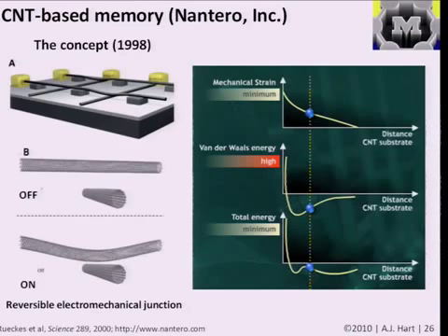And although it's very difficult to make these individual nanotube lattices, and you can't pattern individual tubes so precisely, what the company ended up doing is creating nanotube fabrics, and then using lithography, top-down processing, to cut them into very narrow ribbons, creating little strips of nanotubes that each contain many of them but behave in the same way. It's honestly not as dense, and not as inexpensive as the flash memory that we have, but for some applications, like things that go in space and take a lot of radiation, or need to operate in very extreme environments, high or low temperatures, because of the properties of carbon nanotubes, they've been an attractive product. So Nantero is still around, but I think they've ended up feeding a lot of space and defense applications rather than consumer applications.